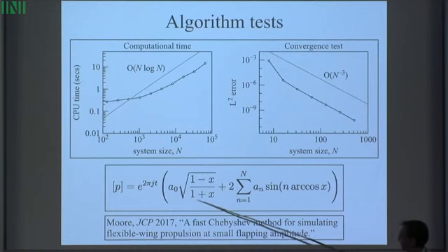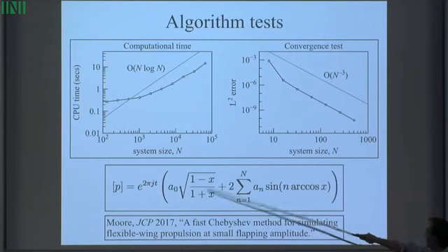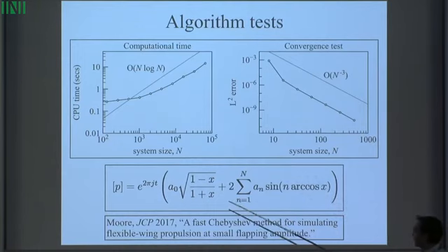I should point to this term. The leading edge of the wing at x equal -1. The fluid force is singular there. So that actually limits the convergence of my spectral method. And if you do the calculation, you could actually see exactly why it is third order convergent. So that's been verified by this test. Okay, third order is still plenty accurate enough for me.